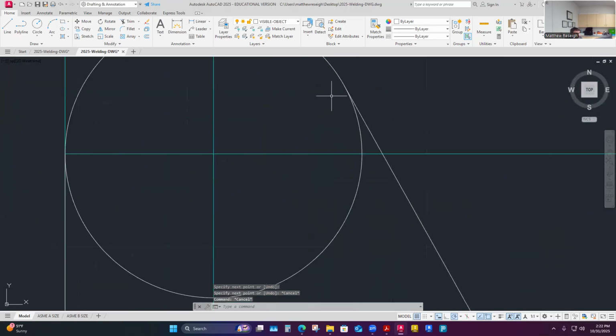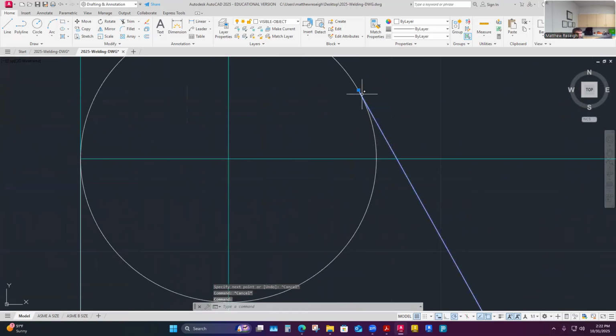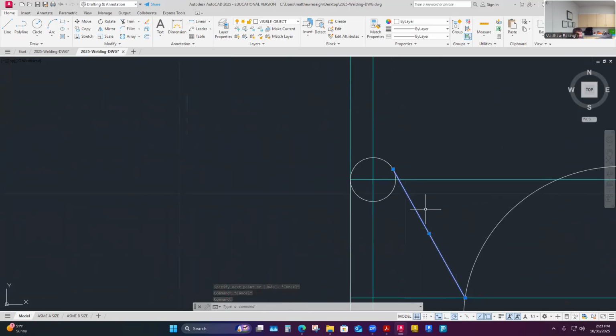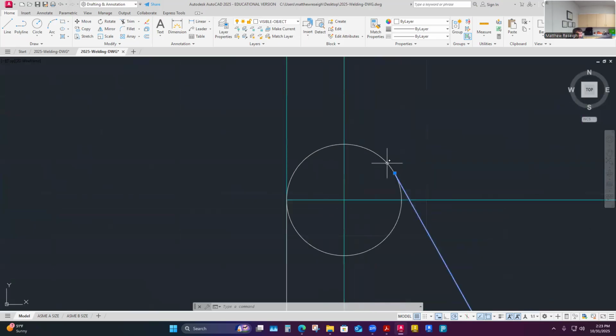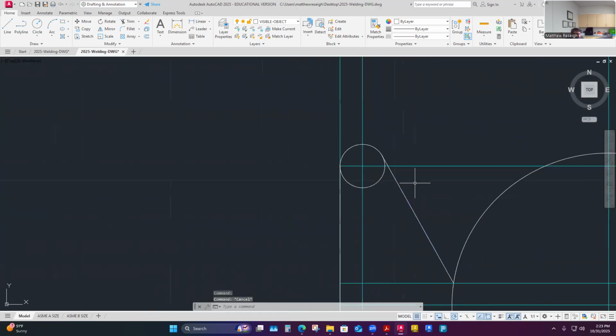one point, right? If you remember from your mechanical drawing class, there's only one point in space where this line, driven by these two points, and there's only one point along the circumference where those two shapes share in common. That's critical for a machine to interpret, that it knows that point of tangency is just one XY value. And then from there it traces that arc and then it hits that point and it cuts that line. So yeah, that's pretty cool.